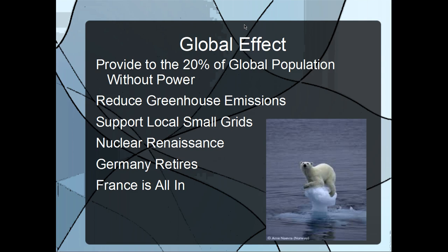France, on the other hand, would be an ideal nation to implement small modular reactors. As it stands, France currently gets 75% of its electricity from nuclear power, and electricity is the nation's fourth largest export. With such a large portion of its electrical needs coming from nuclear power, France is unique in that it employs its nuclear fleet in a load-following sense, meaning that as demand lowers, some plants are forced to lower their electrical output in order to maintain grid stability. Due to the fact that reactors have behaved differently at various times in core life, this requires a large amount of coordination between the various plants and their operating and refueling cycles.